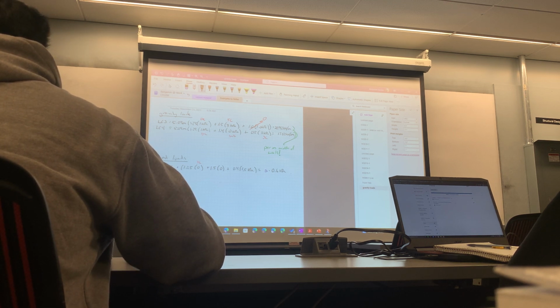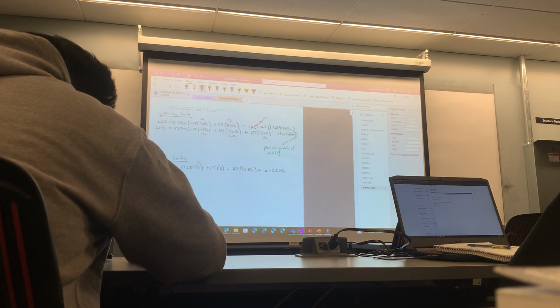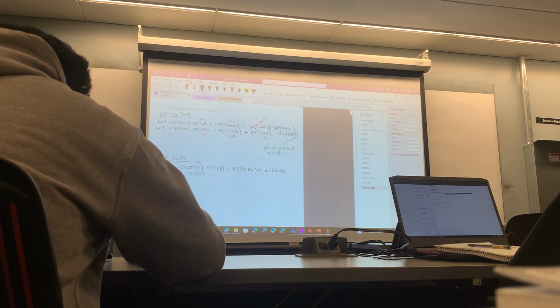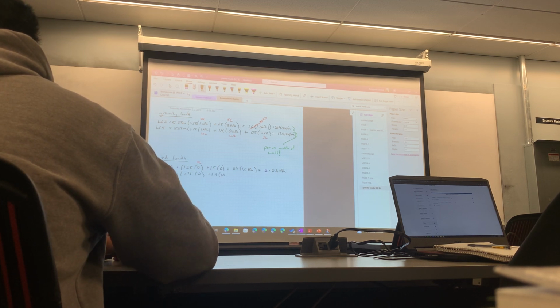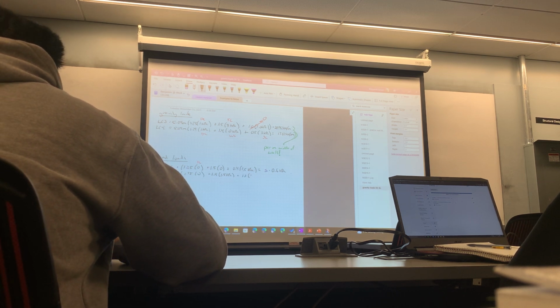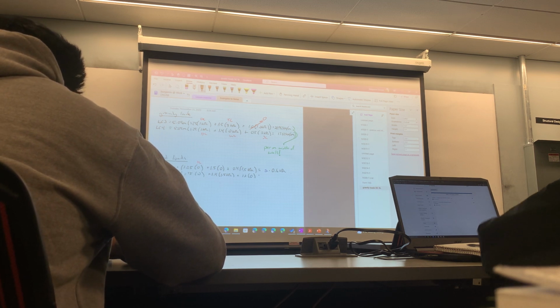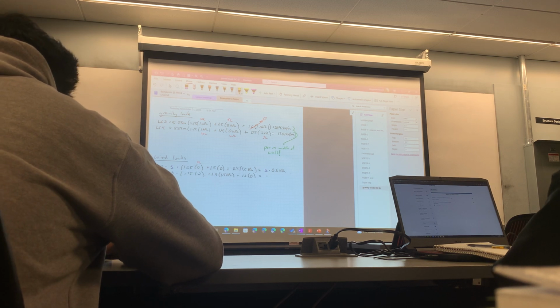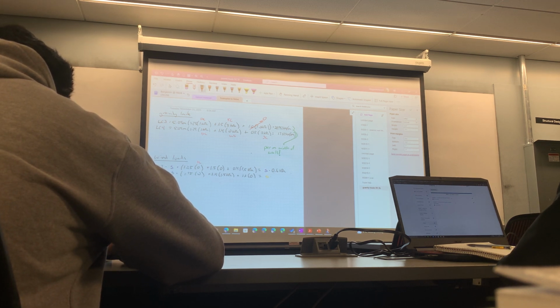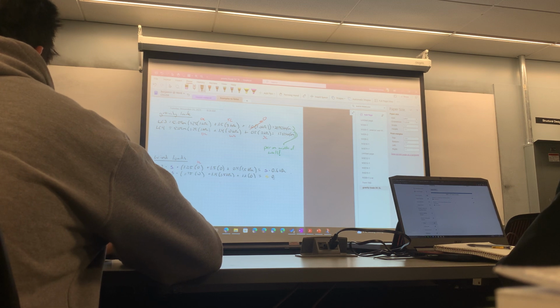For load case 4, we've got our variable again. Is there any dead load? This is going to be maximum wind, so we're going to have 1.5 kPa plus 1.0 times snow. Snow is 0, and that's going to be, I'm going to use a different color here to make it stand out a bit better, S times 0, 2.1.